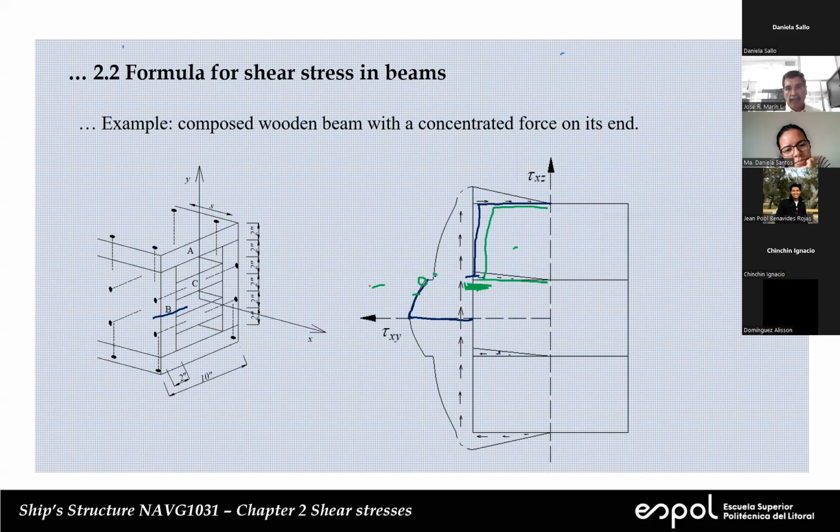This cut here, then this is the value that we're going to go. Because from here, I do not include the intermediate flange, only the same piece of the web and the upper flange. So there is a difference. Now, if you plot not the shear stress, but the shear flow, then you will have continuity. That means that this value here is going to be equal to this value plus this value here.